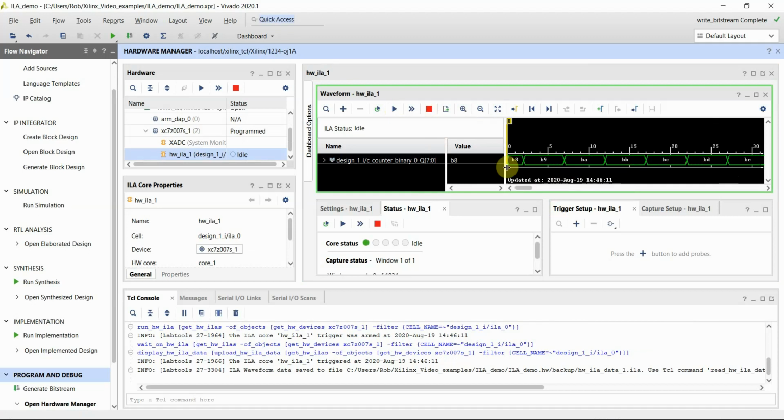Any of your signals in your design, you can connect up to IP blocks, and you can monitor what's going on inside that device without having to actually assign those signals to output pins and then hook them up to a logic analyzer in your system, which can be a real bear when you've got devices with hundreds of I/O pins that are fine pitch in a BGA. So it's a really powerful feature that they have here.